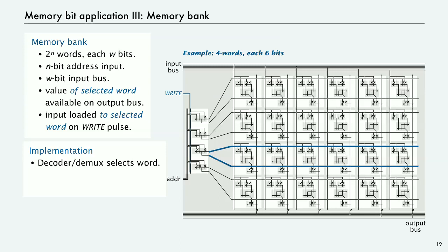That's why we call them selection lines. The address selects which part of the memory is going to be active. In this case, write enable is high, so they're both 1. If write enable was off, then the top one would be 0. But either way, only that word, in this case the bits are 1, 0, so word 2, is the one that's selected.